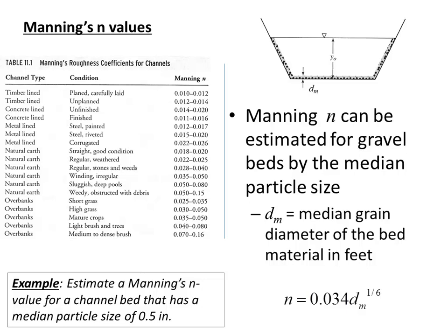And the interesting thing is that if you compare that N value of 0.02 to the table, there's a lot of other materials that aren't necessarily gravel-lined channels that will have a similar roughness value. So, for example, riveted steel may be 0.02, and so you'd have to think, what is it about riveted steel? You'd think steel is more smooth than gravel, but perhaps it's the effect of the rivets themselves imparting some resistance similar to the way that gravel might, or even for just a natural earth channel in good condition, and so that would be bare soil.